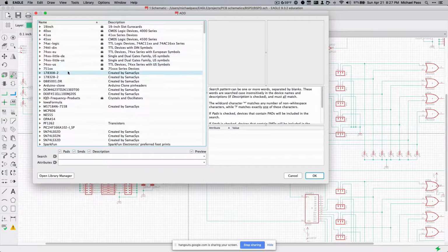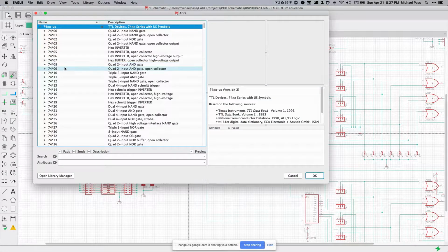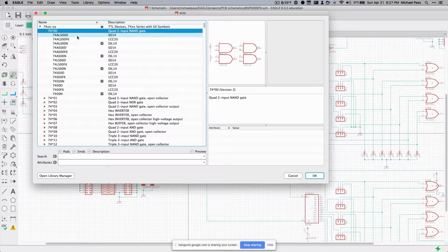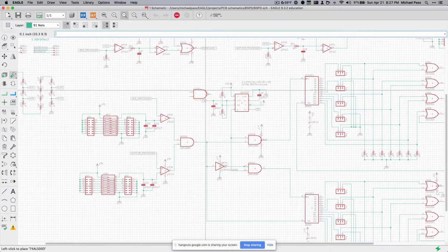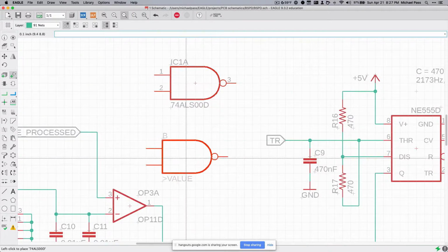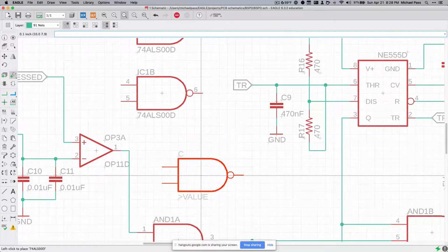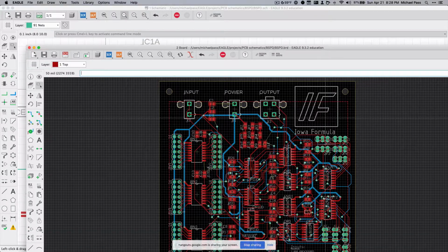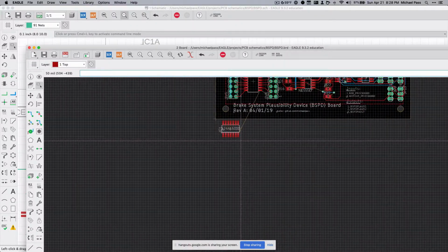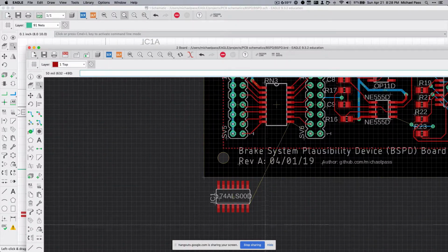EAGLE has what are called different add levels, which are, when you're designing, so a chip will come like this where it has 4 different NAND gates on it, but from a design perspective, I don't want to add all 4, I just want to add one thing at a time, and then, if I don't use the other gates, then they just don't get connected. And anyway, for my bill of materials, there are 2 gates that I just added, but there's only the 1